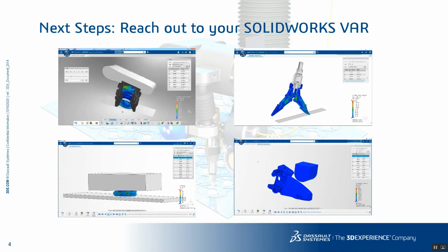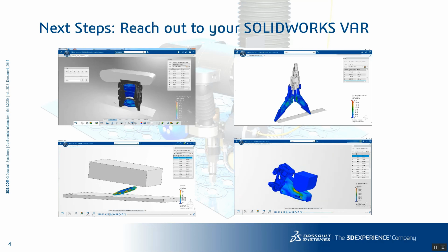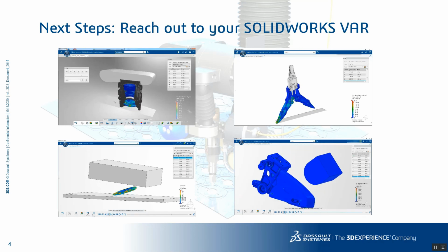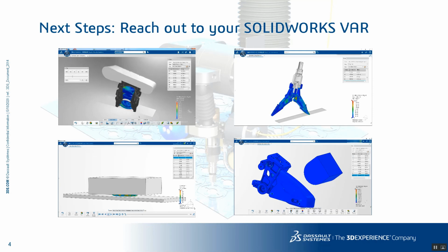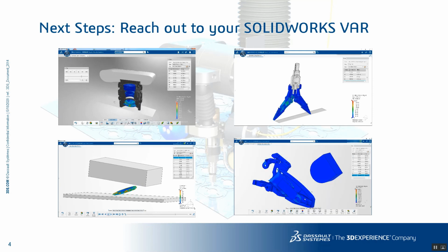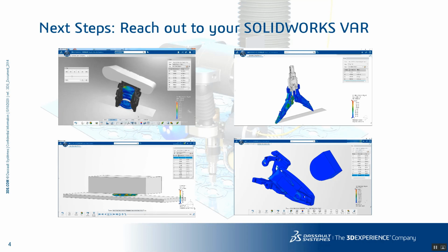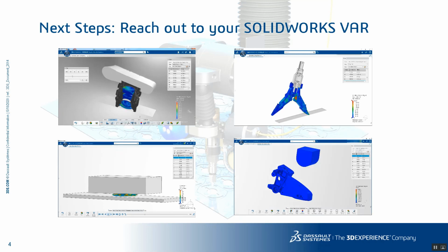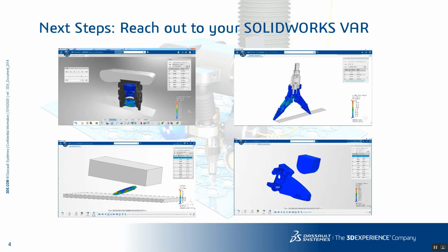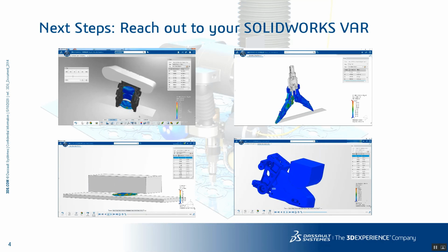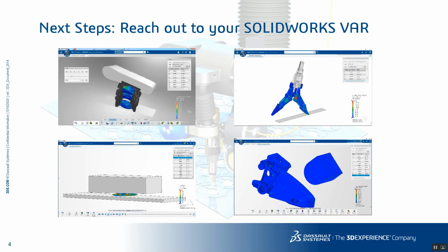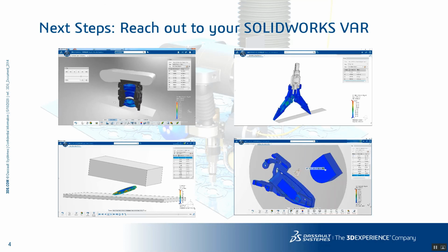And here are some actual examples of the tool being used. So I believe all these are using Structural Mechanics Engineer. They all look like explicit examples. Drop test there at the top right. Can crushing. It looks like an impact test bottom left. I'm not sure what the top left is, but it does look like it's a dynamic simulation. So I think they're all probably using the explicit solver available in Structural Mechanics Engineer.